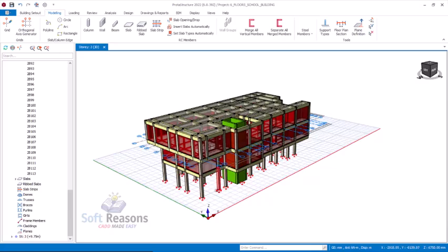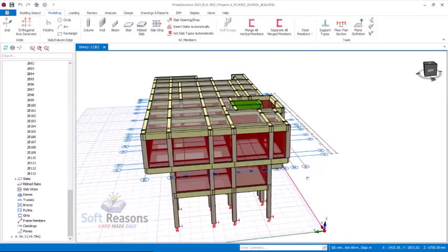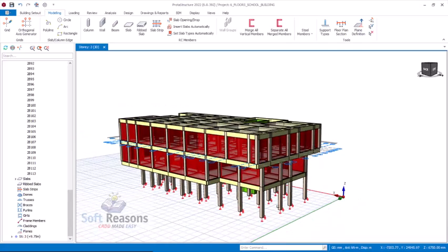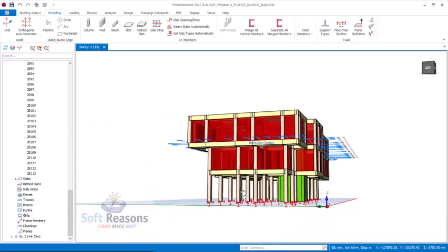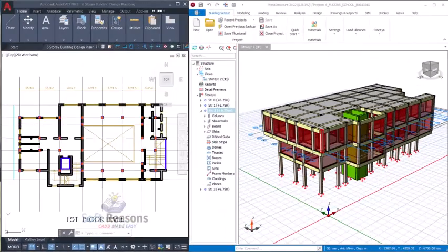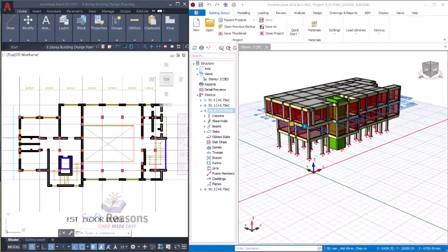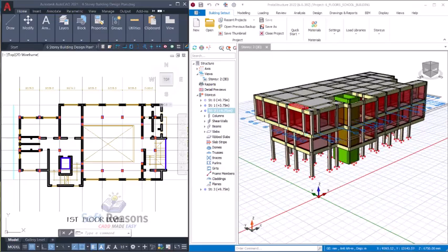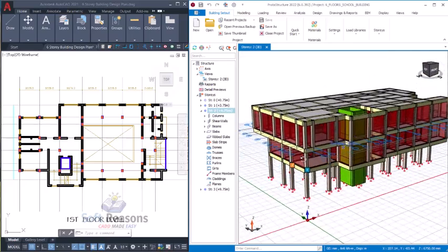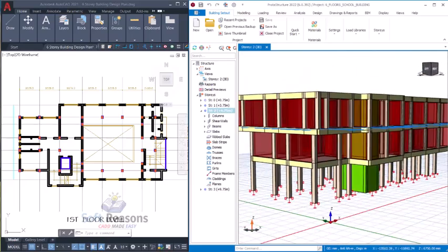So at this point, the story 3 design is going to be replicated for other stories successfully. So before we proceed to generating the third floor to other floors to complete the 6 floors for this structure, we will have to reduce the wall load by removing wall load from a wall that is not supposed to carry a load. Okay, so we start from the first floor.